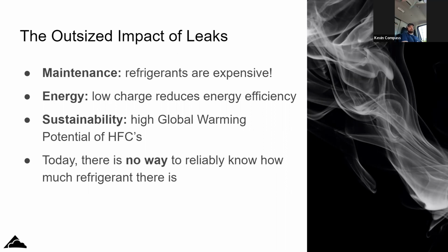And with the guys that don't give up and keep diving into it, generally the leak is usually the last place that anybody's going to think to look, on top of a walk-in or in a space that nobody's going. So just getting up there and going in these places that people don't want to go, that's generally how you find these leaks that have been there for a while, hidden on top of walk-ins or in walls. Or just taking your time and shutting off the equipment.